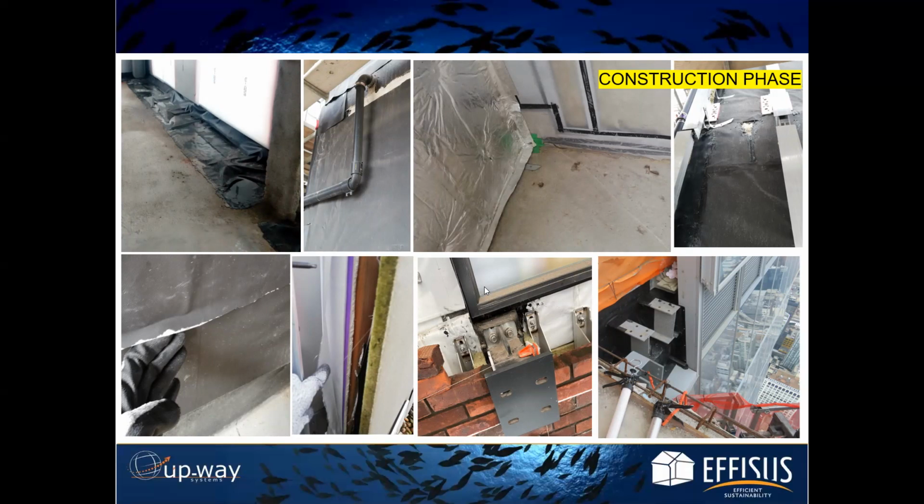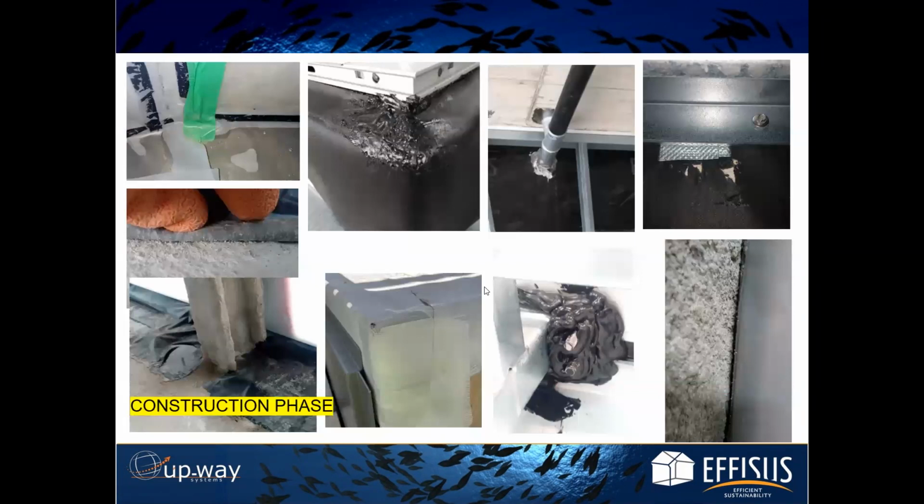And also, I believe, which is a very important factor here, working on exterior exposed to weather situations and lack of space will all lead to problems that I'm mentioning here. In addition to those, I would say water accumulated on slabs, poor corner sealings on window systems, also membranes that are damaged, poor corner details, and interface joints that are not done properly.